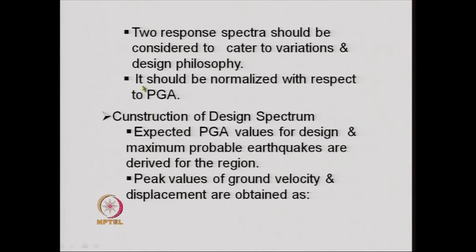And next, the response spectrum should be normalized with respect to peak ground acceleration, because if you want to prescribe a design response spectrum, it should be prescribed in the form of a shape, but the actual response spectrum would be obtained after we multiply that shape with the peak ground acceleration, which may differ from place to place.